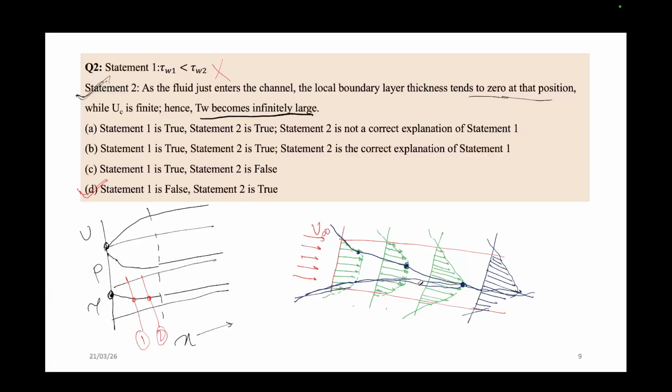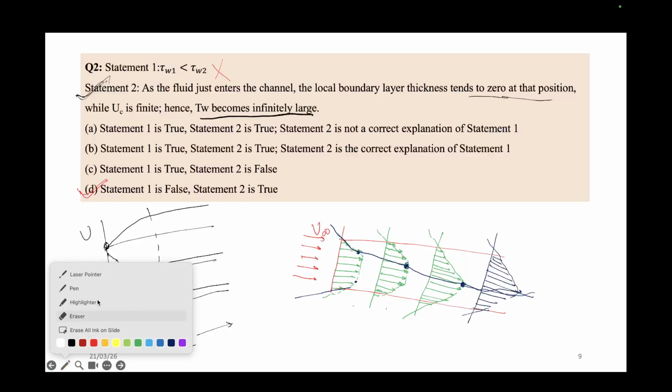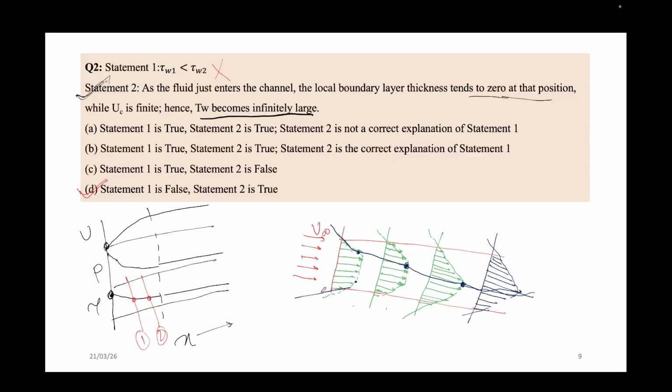You got it or not? This is an imaginary line that connects this point, this point. So at this point, you see here from both sides the thermal boundary layer merges. So that means from this region I can say that it is fully developed. That means after this there is no change in the profile you will observe. But before this region, changes in the profile you will observe. Got it?